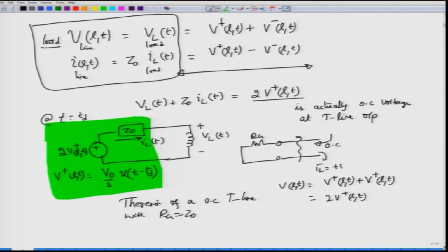How do I do that? Well, this is an inductor. What is the relationship for an inductor in terms of the voltage and the current? For an inductor, we remember that if VL is the voltage across it, IL is the current through it, and the inductor has a value of L, inductance, measured in Henry, then the voltage VL will be equal to L dIL by dt.